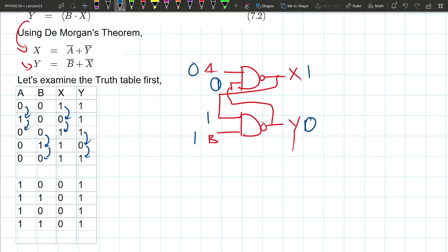I'm going to start off with, instead of starting off with A being 0, I'm going to start off with A being 1. Okay? And remember, when A is 1, right, this is the valid state for the flip-flop. Right? So I'm just going to copy that down. Okay? But instead of changing A again, I'm going to change B from 0 to 1. Okay?